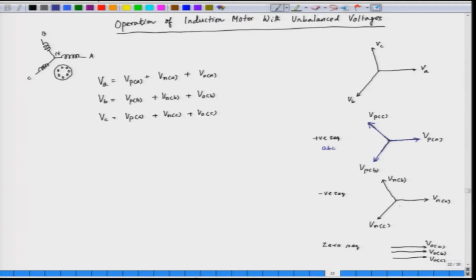But in the negative sequence component, this is phase A and phase C is lagging behind phase A by 120 and phase B, which is here, is lagging phase C by 120. So, in this case the sequence is ACB, not ABC, but ACB. But for the 0 sequence component, all the phases have the same phase. So, this is cophasal. This represents the cophasal set of vectors.